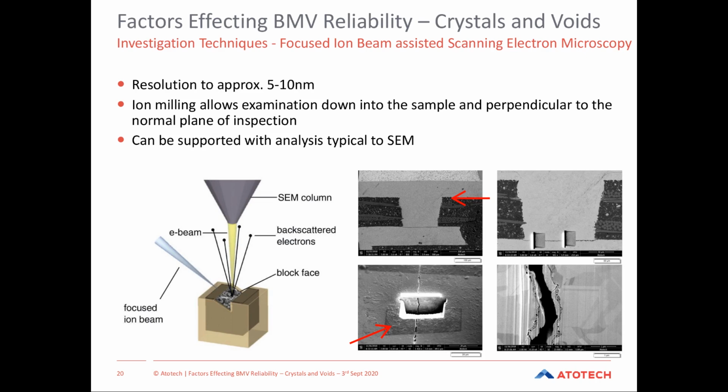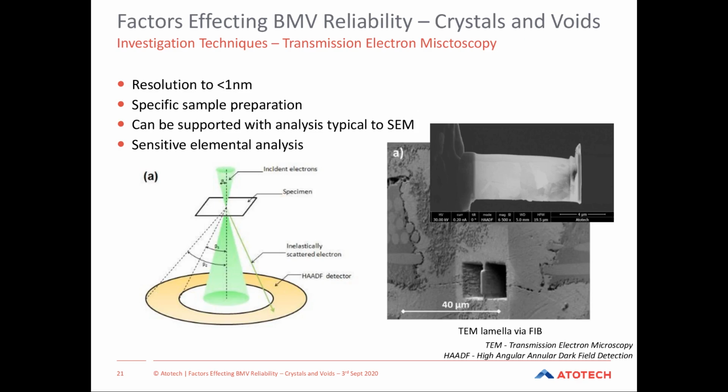But unfortunately, it limited us in developing our knowledge around recrystallization and nanovoids especially, which is why we moved to a transmission electron microscopy system instead. With a TEM, as the image here is showing, you use 2 FIB cuts to create a very thin sample. These are about 60 to 100 nanometers in thickness, which you then break out and put into the TEM unit.